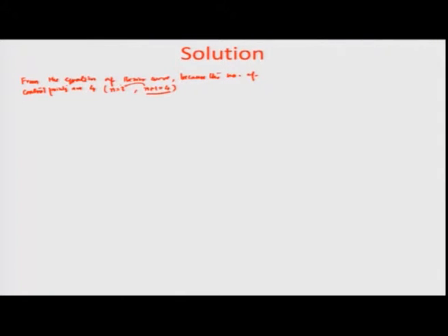So, the curve function looks something like the sum of I varying from 0 to 3, of 3 factorial by (I factorial times 3 minus I factorial), t to the power of I, (1 minus t) to the power of 3 minus I, V I, where V I are the control points. The control points, as you know, are V 0, V 1, V 2 and V 3, respectively 0 to 3.